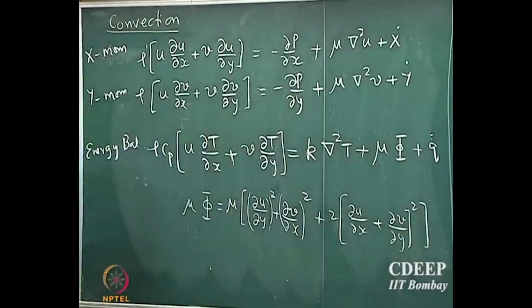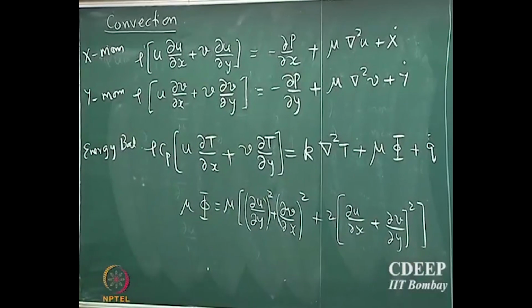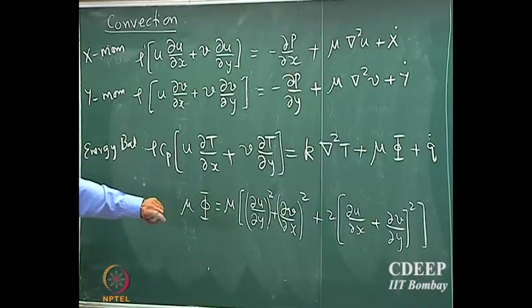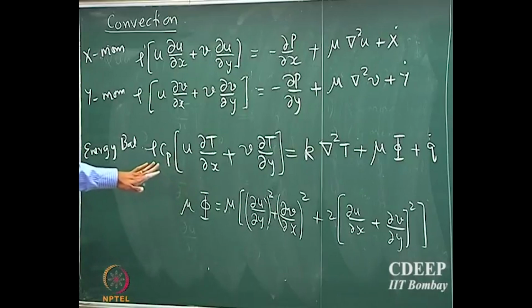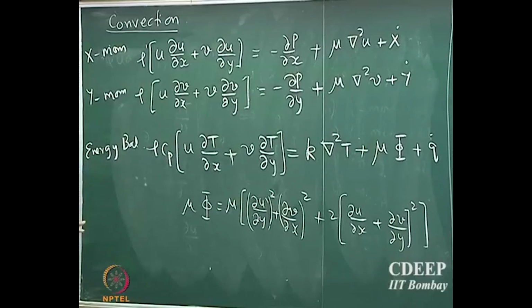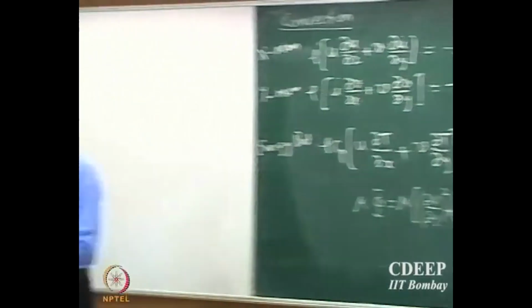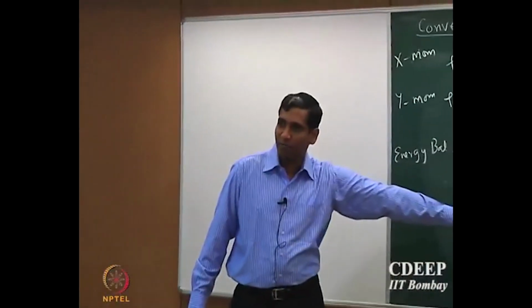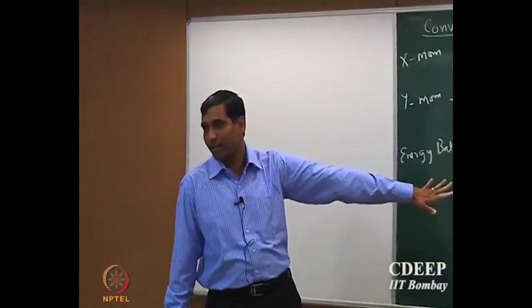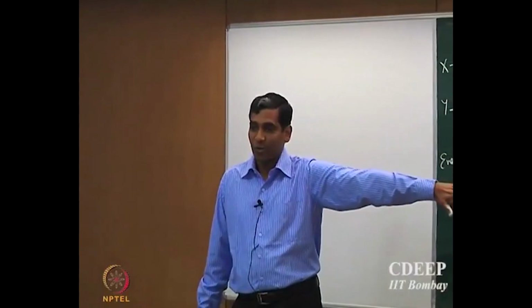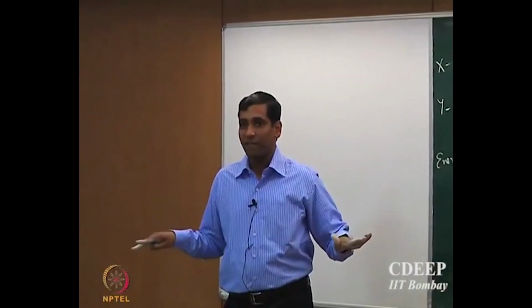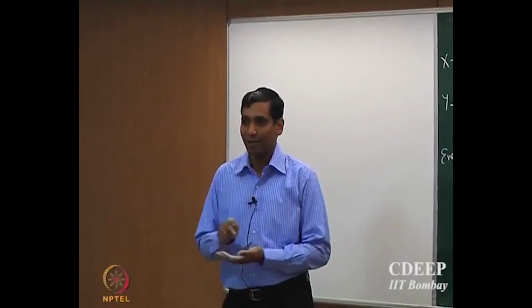So that's viscous dissipation. Okay. So this sort of completes the energy balance. Again you can get the same thing from Navier-Stokes. All that we have done, you can use shell balances and reach the same expression. You can write the Navier-Stokes and reduce it, you will get the same expression, and you can also start by describing different processes. So it's all equivalent if you do it properly. That's very important, if you do it properly.